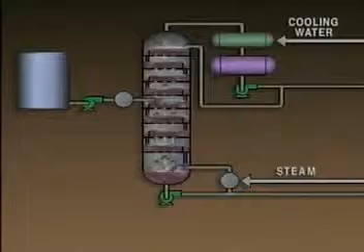Now, changes in the tower's differential pressure may have other causes in addition to the ones we've identified. So it's important to carefully evaluate any situation before corrective action is taken. In this topic, we looked at two key factors in the distillation process: temperature and pressure. Remember that although we discussed them separately, temperature and pressure work together. Both of these factors must be correct for the distillation process to work properly. Now, try to answer some practice questions to check your understanding of what we've gone over.